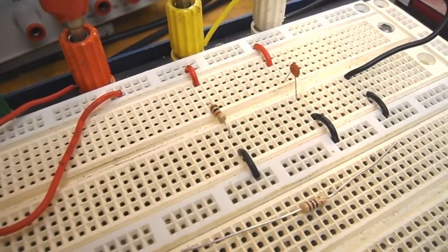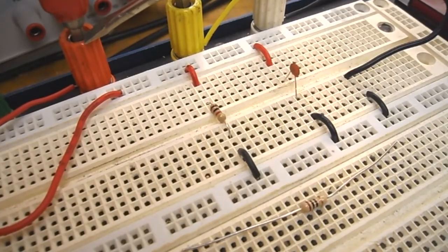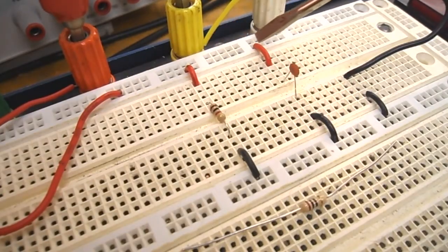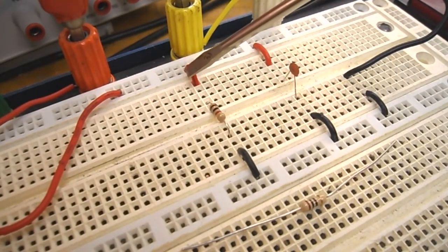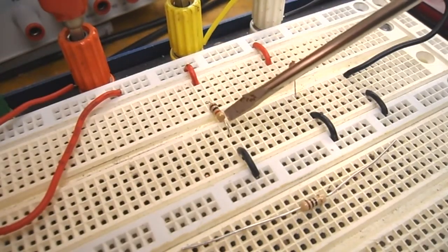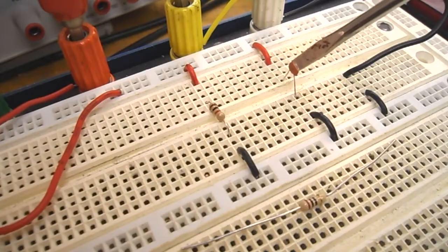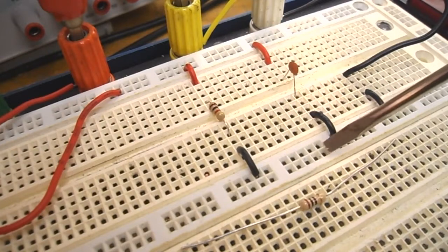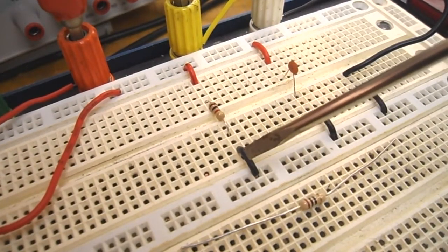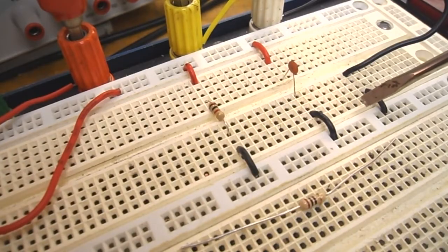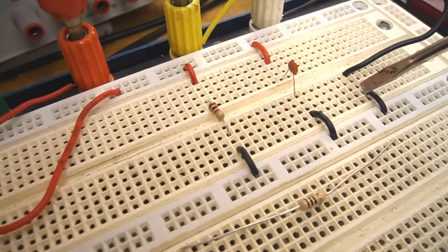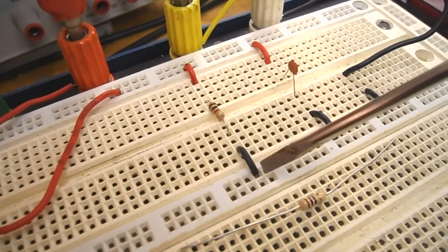I just want to show you my circuit setup. I have my function generator and channel 1 coming in on the red binding post that goes to this bus line. Remember, it's a parallel circuit. So this is my 1K ohm resistor in parallel with my 10 nanofarad capacitor, and this is my ground line coming in. Now I've used these little links here because this is where I'm going to place this 10 ohm resistor. So I'm going to put my 10 ohm resistor in here, and that's the total current going through my circuit.